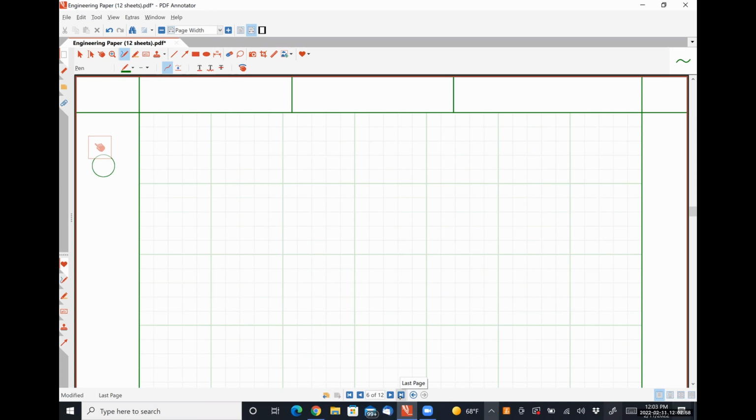Yes. So to best answer that question would require us to look at some analysis to see what role the neutral plays, okay? But the short answer is you can absolutely have a delta Y or a Y delta where the neutral's probably just tied to ground or something like that.